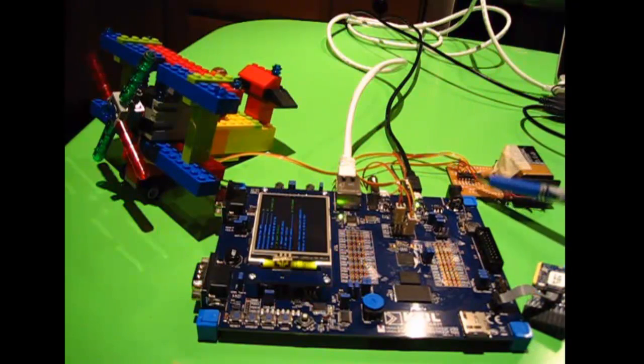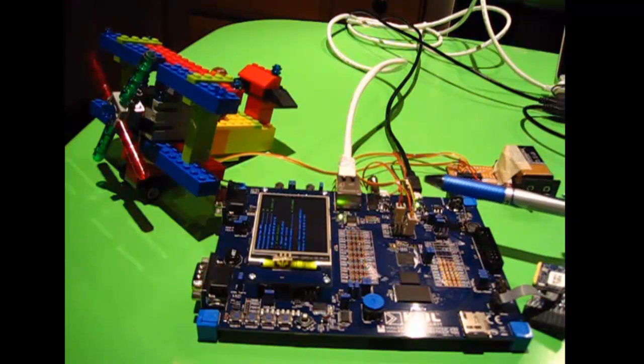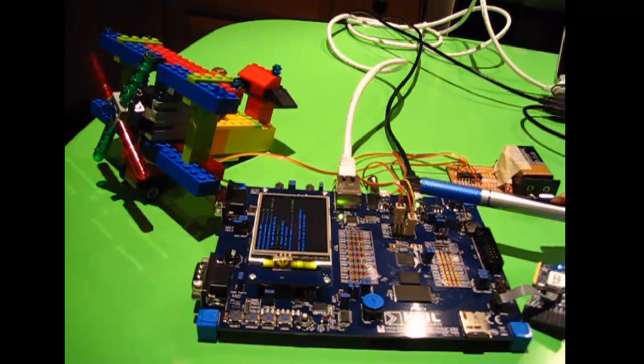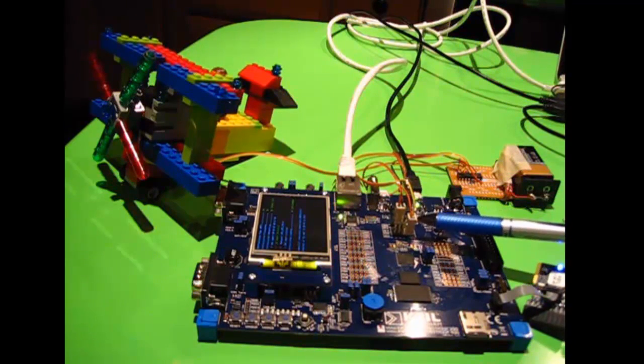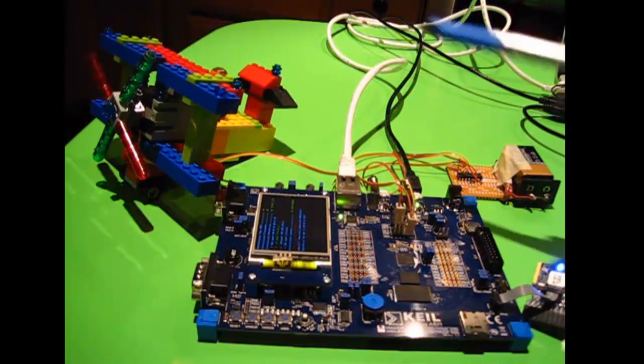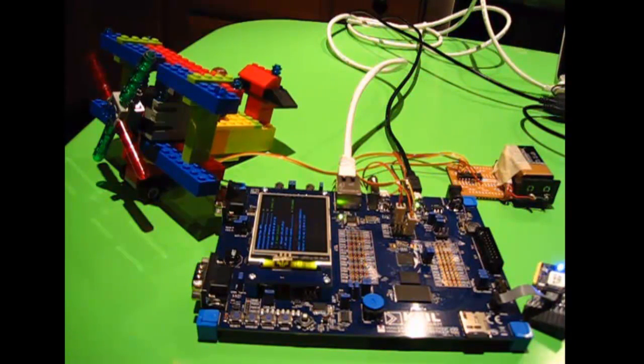This actually will feed an H bridge. The H bridge is allowing us to use the 9 volts from the battery because actually the motor will require 9 volts and the board is only giving us 3.3. So again, we get the power and ground from the board, and we also get the 2 GPIO pins feeding the H bridge, and the H bridge will allow us to power the motor using the 9 volts.